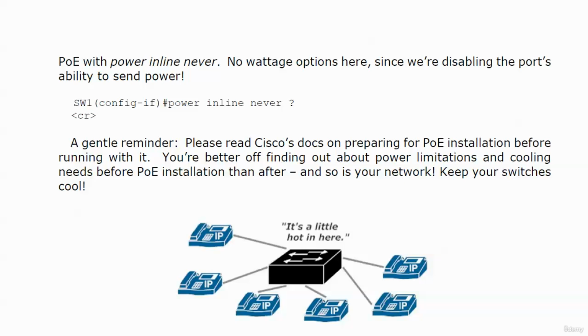This is not just the usual yada yada, as Google once said. This is the real thing. You really do need to read the documentation on preparing for installation before you run with it, because you're better off finding out about power limitations and cooling needs before your PoE install than afterwards, because then it gets to be a little damaging to the switch. And the one thing you don't want to do is void that warranty.